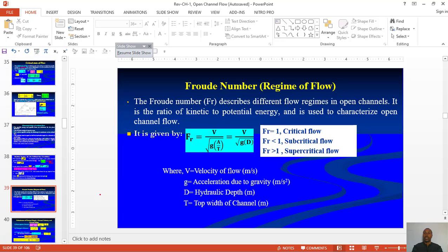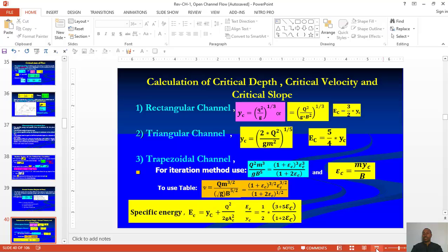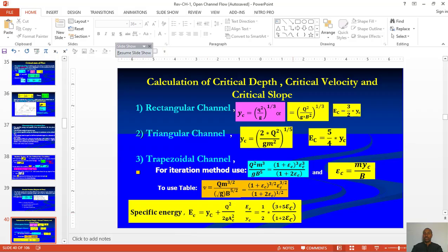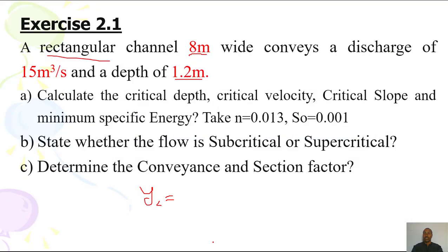This is the critical depth formula for rectangular channel. So you have Q, B, then you can substitute here. Then finally, we can arrive at the solution. For rectangular channel, already we know the formula. Then we can compute. So I think Q is given. Then first you can find small q. Small q will be capital Q over B. This is discharge intensity, the total discharge divided by width, which is small q. Then finally, you can find critical depth.